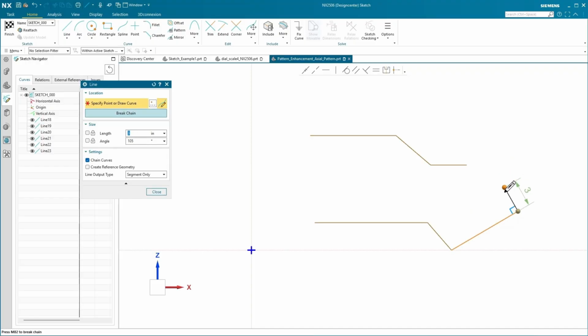All right, so as we go back around, if there's a point that you want to move that you've already placed, so maybe you mistakenly created that point over there at the end of that last curve, and you want to go ahead and move that, all you have to do is move your cursor, the pencil tool, back over until you see the little crosshair indicator over that first point for that previous curve, and you can drag that and reposition that start point for the current curve that you're creating. All right, so now I can create the second point and click down to finish that creation.